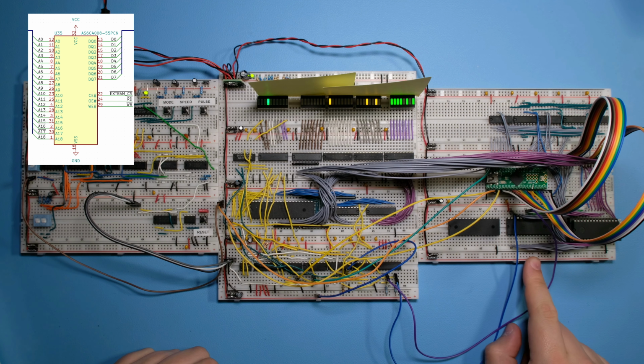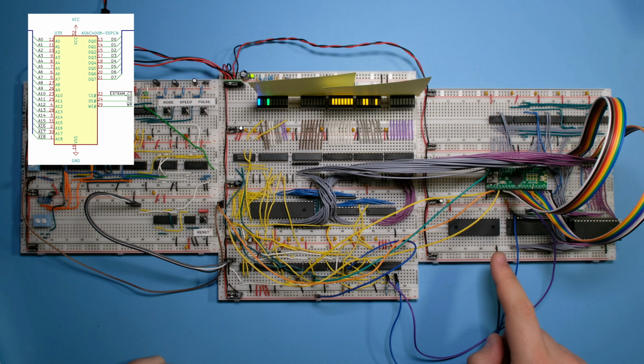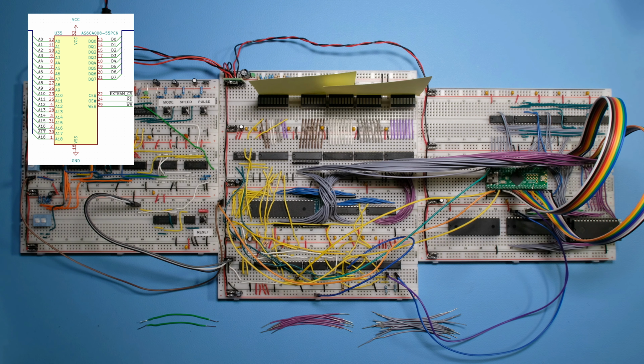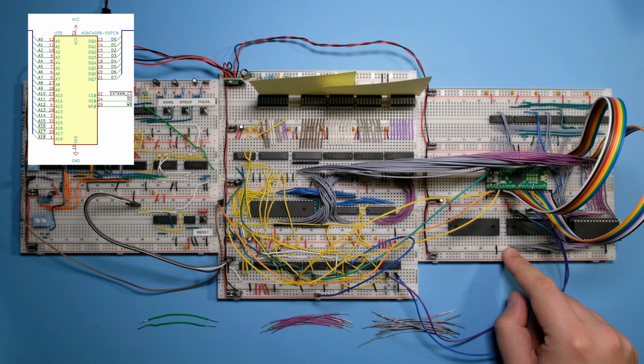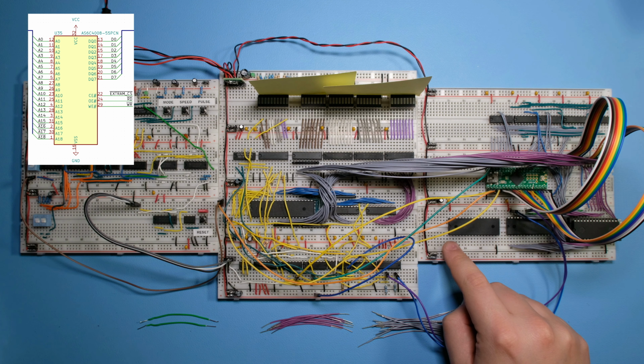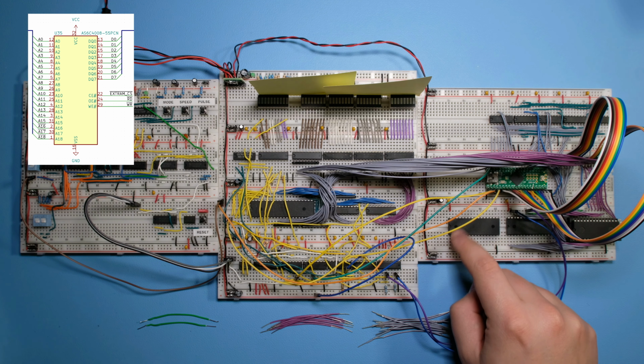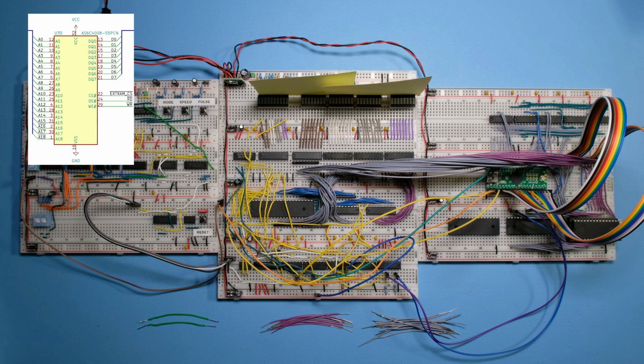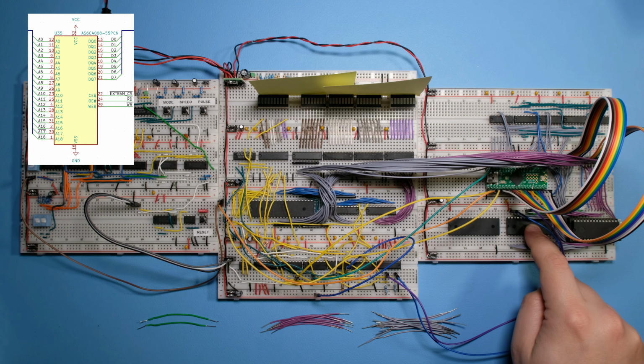Now I'm going to cut all the wires to transfer the address bus and the data bus over. I'll do this off camera. Okay, so these are all the wires to connect the existing signals from the first RAM chip to the second. The pinout is identical except for pins number 1, 2, 30, and 31. And so we can just transfer everything over from the existing RAM chip. So let's do that now.